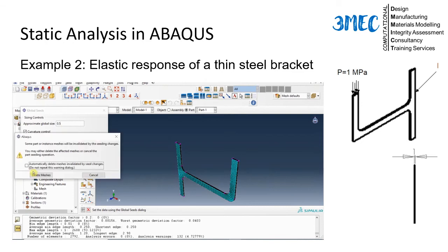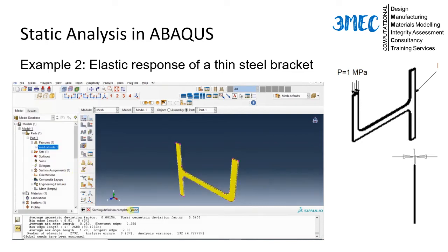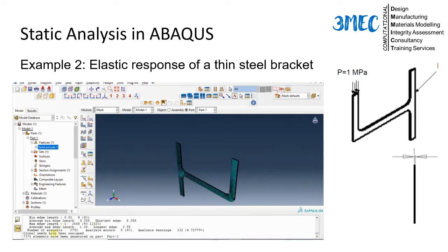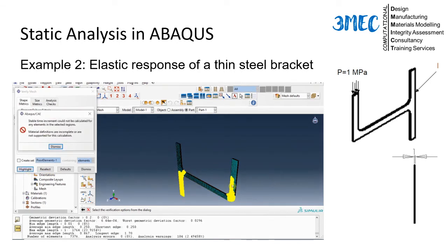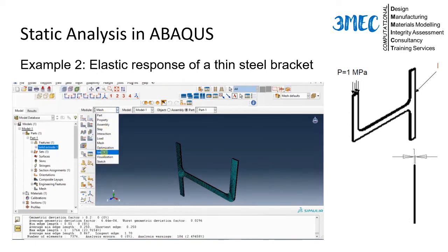Still with this kind of size, with 0.5, let's see how many elements it has. So you have like 7,000 elements. It's a very large number of elements, but still it's 2D, so it may survive. You will see there are highlighted sections, and there are some elements which might have geometric issues. So again, it's your choice. Now it's getting better. Still, it's a small number of elements which have some problems, so you can keep on playing around with this and see what happens.